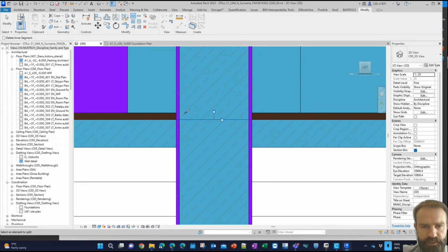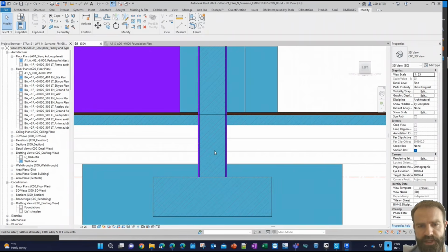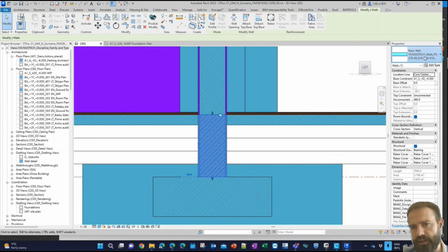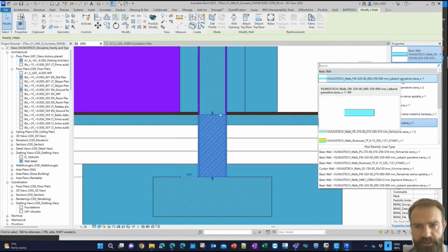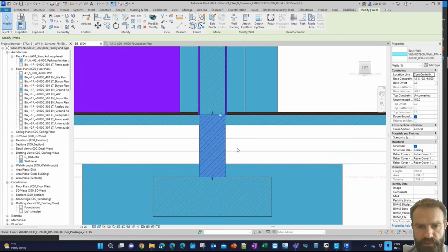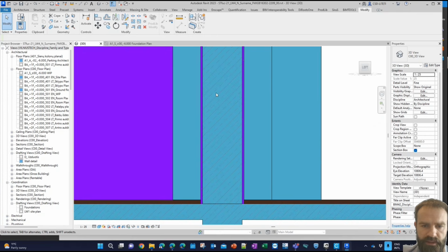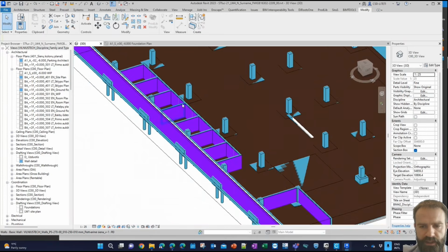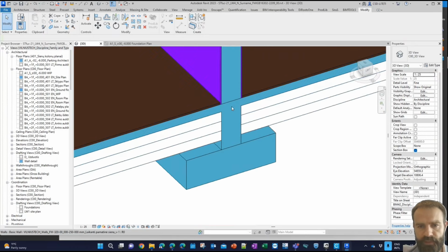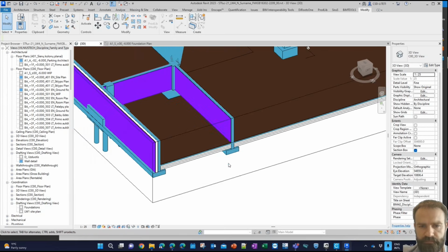So I just click split tool. It creates two separate walls. I select bottom wall, and from the list of walls, I select wall which is this one. So now I can see my wall is made only from concrete, no additional plastering layers, and the wall above this goes with plaster layers. And now I have nice wall for foundation part and the wall inside the building.